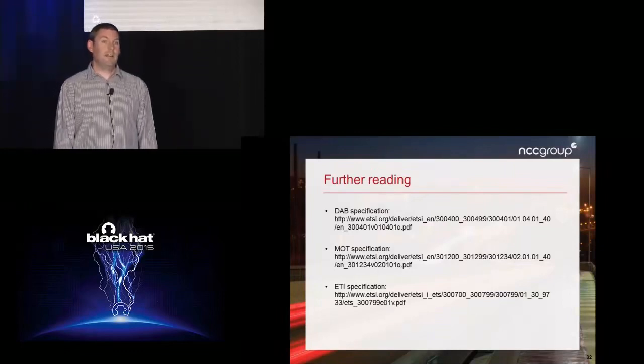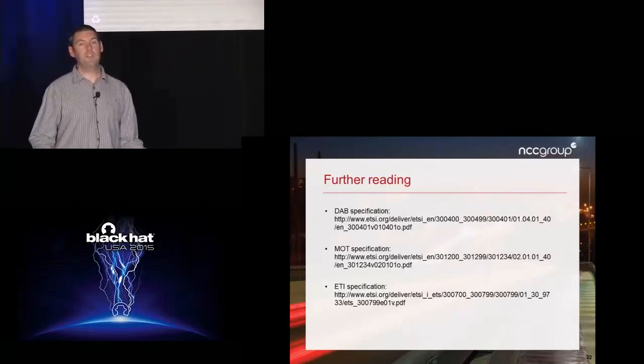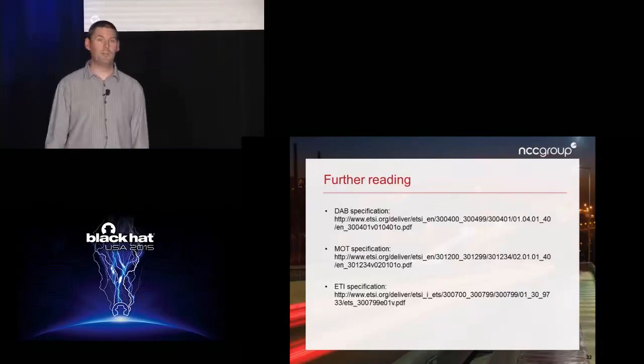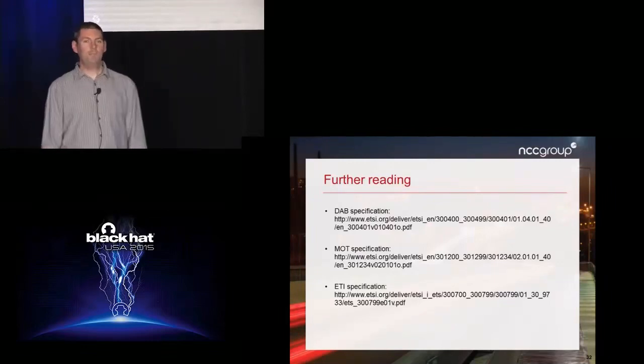Yeah, certainly. If you've got code running on the head unit itself, then you're going to be able to talk to those dbus interfaces if they're then talking onto CAN. There are ways of authenticating dbus. However, it's user-based, and if you are running at the user level that runs the whole infotainment system, it's probably going to be root. So it's going to be game over anyway. Great, thank you.